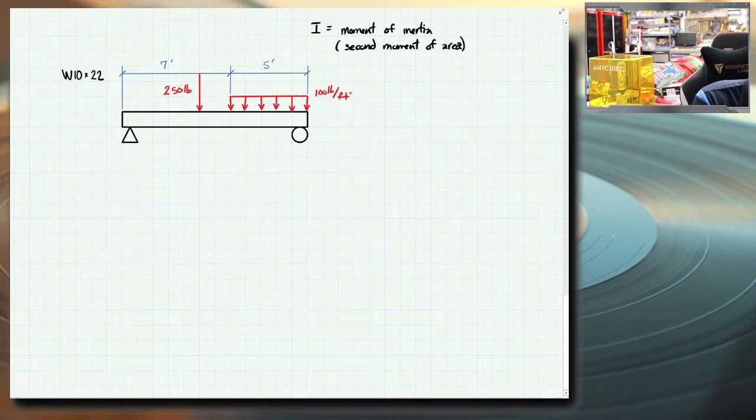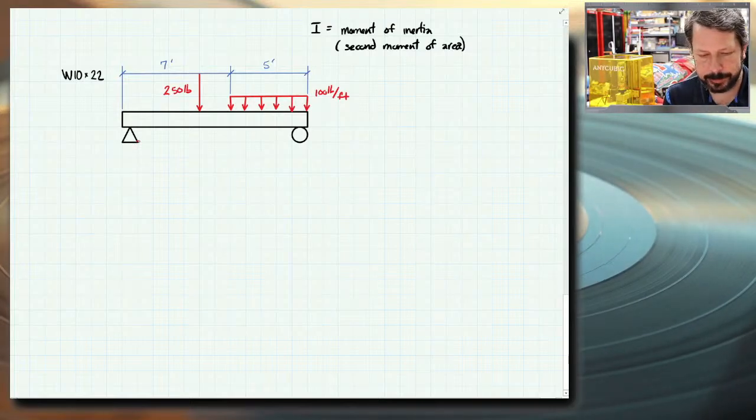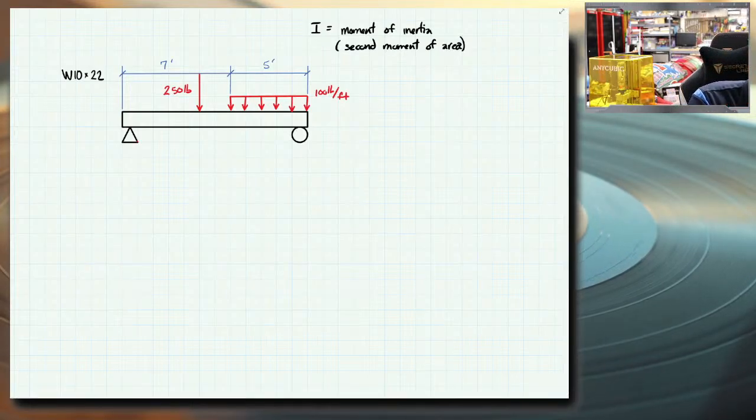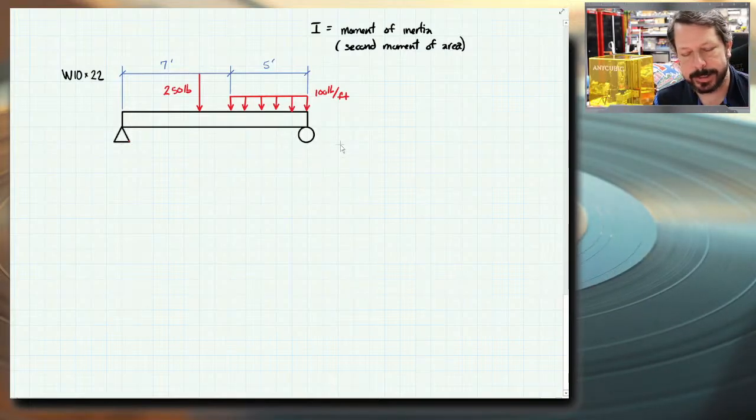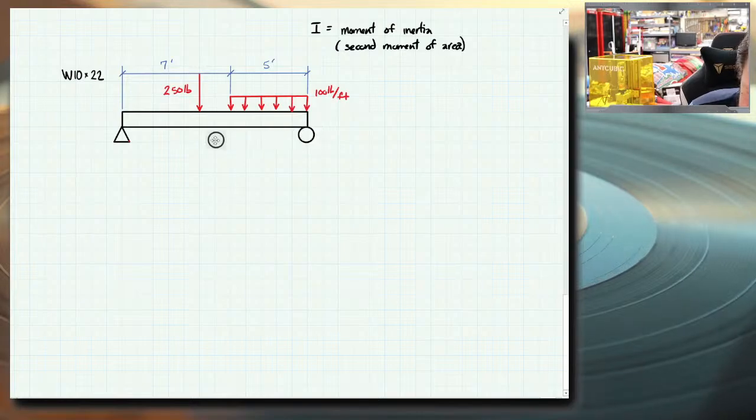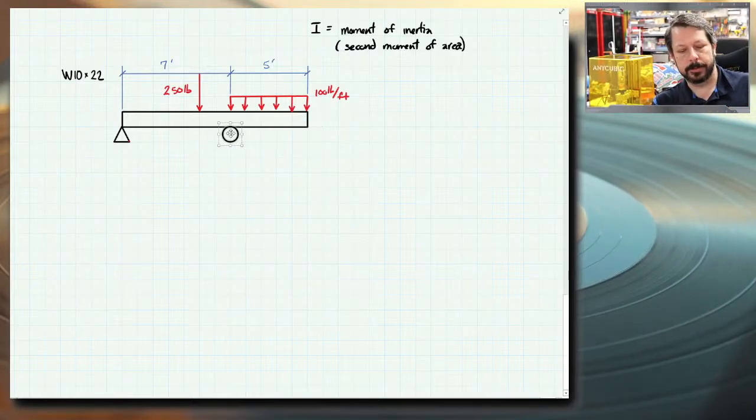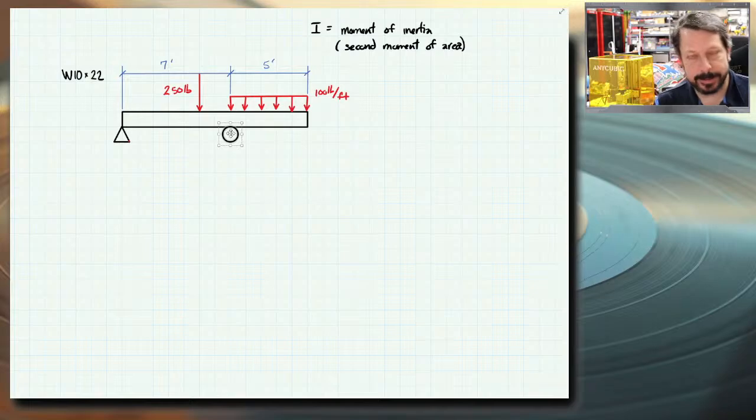Let's assume that I've got the triangle and the circle lined up perfectly on the ends of the beam, so that the reactions are right at the end of the beam. Normally we just ignore the very end of the beam and assume that the pins and rollers are flush with the end, so the reaction can be there. Sometimes you will have a little piece of the beam hanging out. We call that a cantilever, and let's not get into that just yet.